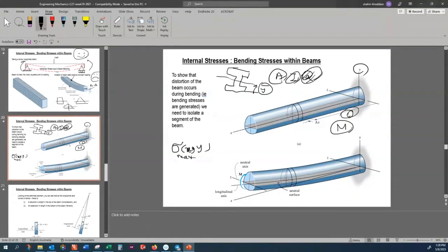As a structural engineer, your job is to find out which point in the structure can grow the crack first. That is the most critical point. And in finding that, you not only rely on X, you not only rely on the M of X; the plot of M of X would tell you the maximum M, right?